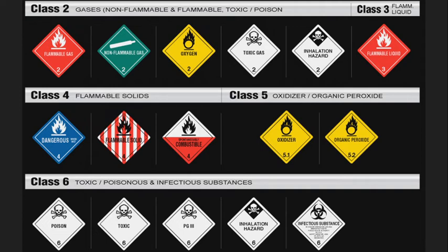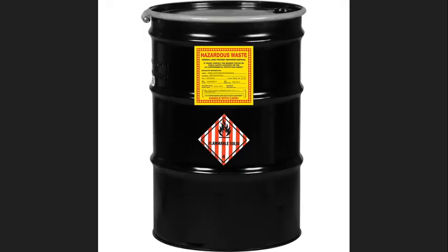These are DOT required, and it is EPA required. And Clean Harbors will send me nasty emails if we don't put these on there. So please make sure if I tell you to put these on there that they get on there. So there's an example of a lovely, fully labeled drum. It's only missing that manifest tracking number, but it's got a fully completed hazardous waste label almost. And then it's got the flammable solid DOT sticker, because this would be like gas and absorbent. Let's say it comes back hazardous for flammability, then this is how we would label it.